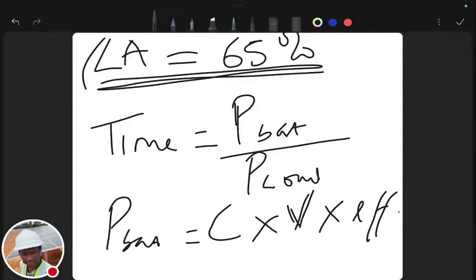Thank you, motivation, for the 87.4%. So you can see that it is more than that. For Blessed Omoleji, you asked whether the voltage is always 12 volts. Well, it's not always 12 volts. The exact voltage kind of ranges around that, but for calculation purposes, we usually use 12 volts. Yes, most of the batteries we use in solar for lead acid are 12 volts, but for lithium, it's not always 12 volts.